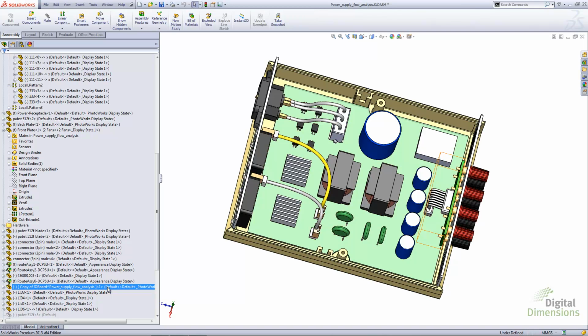Now, a behavior to take note of is that external files within the top level of the assembly are candidates for becoming virtual components. If you have components that are within the subassembly, you will have to open those separately and then make those virtual in turn.